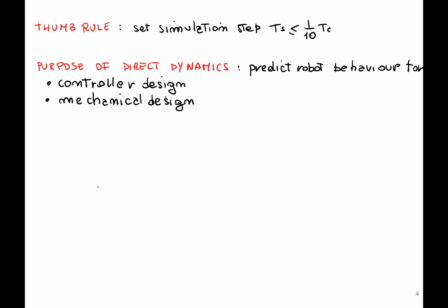So your customer requests some specifications. It says the robot I want you to design needs to be able to do this motion, going from here to there in a certain time. So it needs to have a certain acceleration, and it has this structure. Given this, you can check what the necessary torques are, and then select the actuators according to the requested effort.